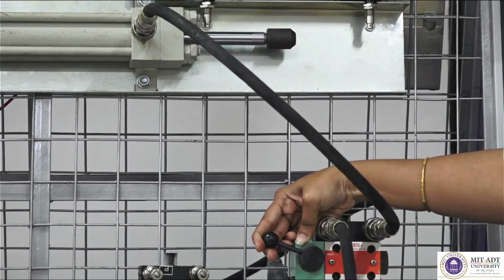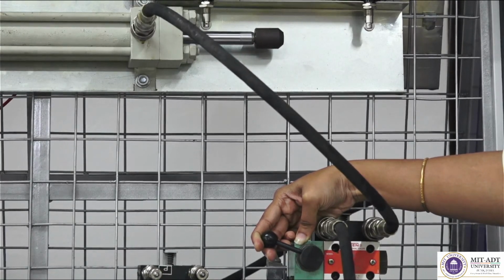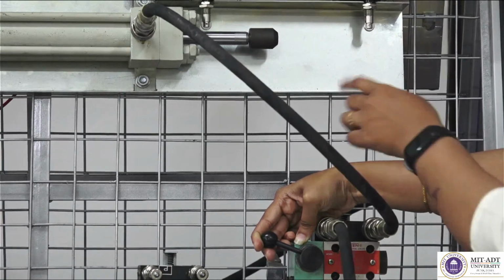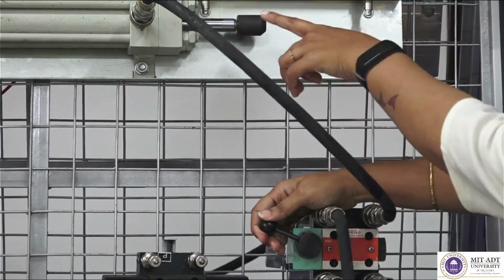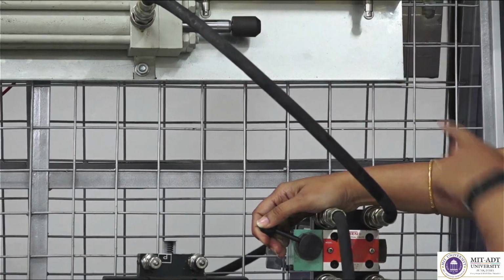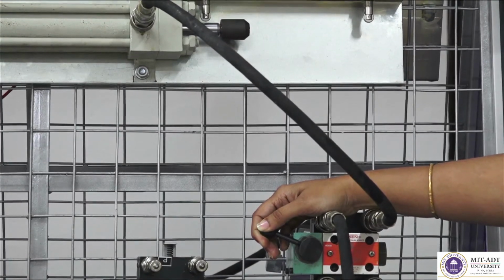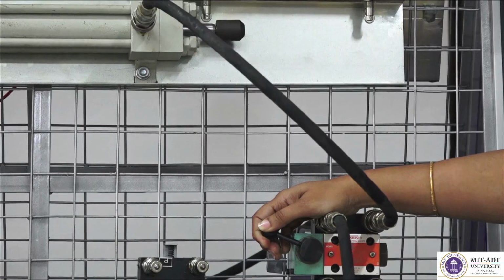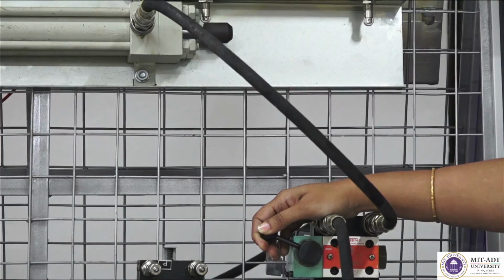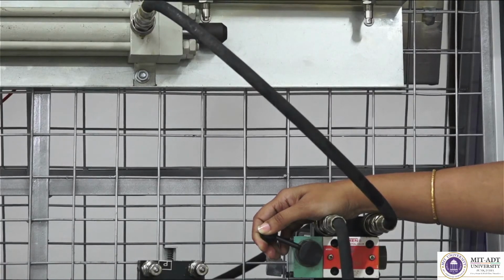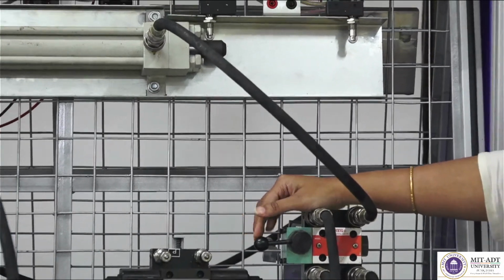What I am going to do now, there are these roller switches which are going to actually sense the movement of this cylinder rod end. So, once this rod end reaches that end, these roller switches are going to sense the motion that the end stroke has happened and now it is ready to switch the position of the DCV, which means retraction has been completed and now we are ready to go for extension.